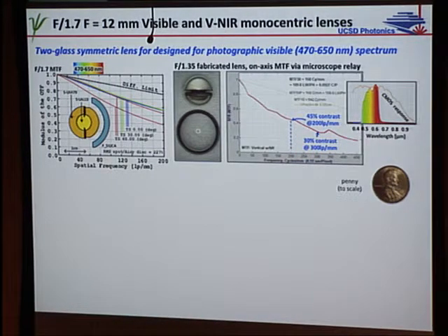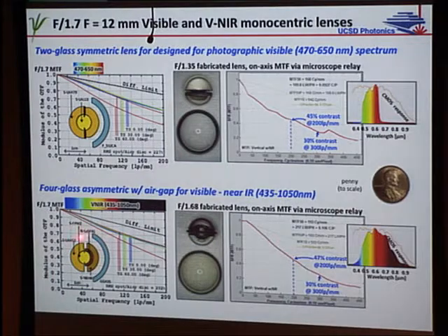That's really good. And a more complicated lens, this is actually the more complicated lens, including that internal air gap for spherochromatism, let us spread the response out to the full CMOS sensitive band. So this is a camera lens intended for a monochrome, night vision-y sort of starlight imager. And the resolution was maintained despite the increased spectral band.